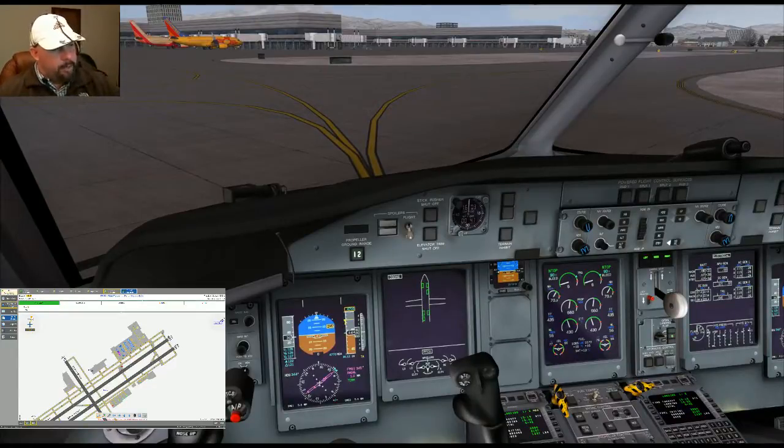Again, one more time, that was the RNAV RNP Zulu into runway 34 left at Reno. The purpose was simply to demonstrate the ability of the Majestic Software -8 to fly radius to fixed legs, and it did phenomenal. The only hiccup we had on that flight was caused by me. I didn't set up the VNAV correctly, leaving the transition waypoint into the approach, but the plane flew it marvelously.